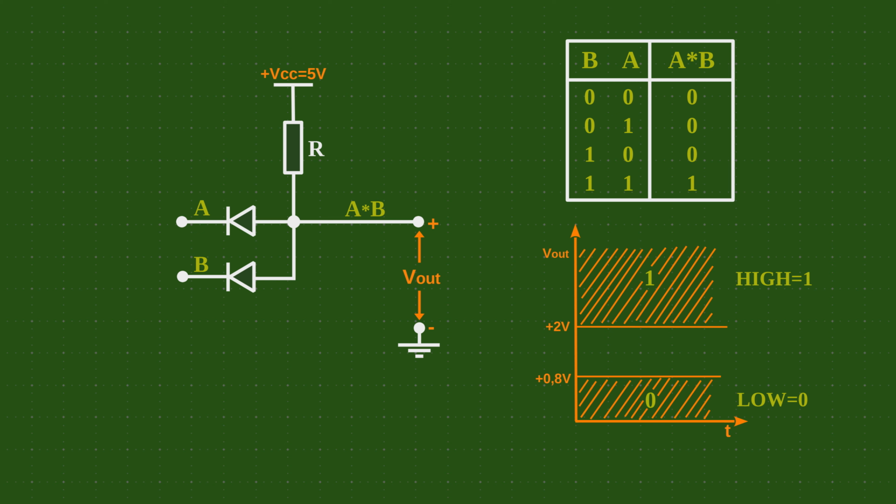By measuring the output voltage level we can determine the output state, high or low. There is also a third area, and that is the forbidden area. This means that any voltage between 0.8 and 2 volts is not usable and as such represents nothing. However, it can cause malfunctions, and therefore this area is not used in digital electronics. Now we can go back to the AND gate.